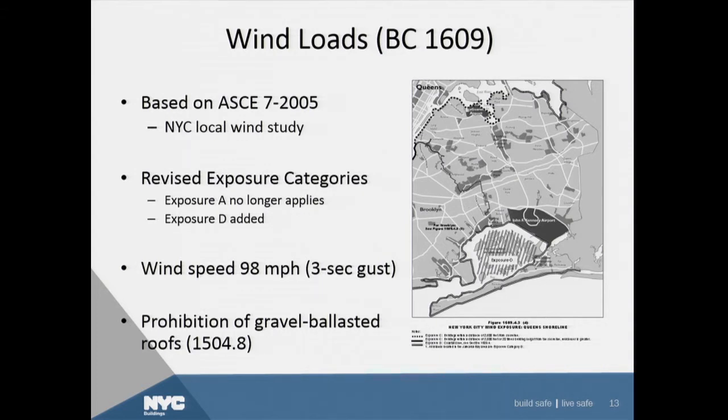And this comes mainly as a recommendation from the National Council of Structural Engineering Associations. They have gone through and done post-hurricane assessments in many countries, not just the US, but many locations, and they've seen the impact that such small particles can make, as they can end up being projectiles that cause damage downwind of the structures that have the gravel ballasted roofs. Okay.